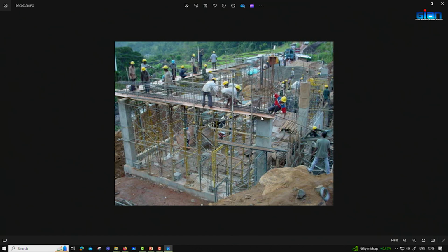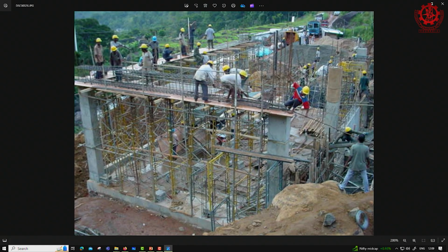We want the powerhouse to have a heavy weight, right, because you know that when the pressure from the penstock water comes onto the powerhouse, it should not slip. So, it should be well pinned to the ground, because you can see the penstock will have such a big pressure and push the powerhouse down. So, it should be very well connected to the ground or to the rocks, right. So, we use a concrete mass to make sure it is heavy and connected to the ground.